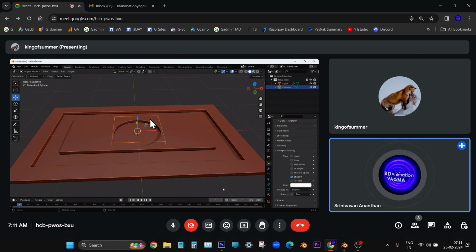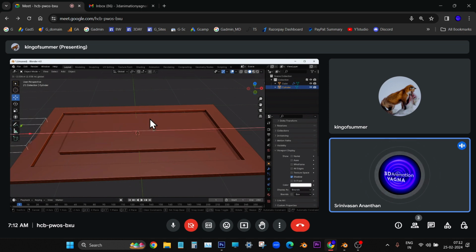Now just for fun, move whatever you have selected, the cylinder object. Move, undo. Whenever you are just moving it for trial's sake, immediately you should undo to get it back. Now press the x-axis handle and move it to the right side and left side and just see what is happening. Yeah, the hole can be transferred. Yeah, this is what a Boolean operation is.